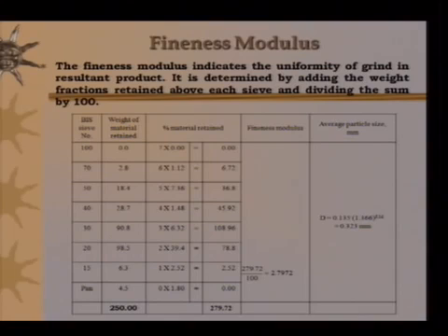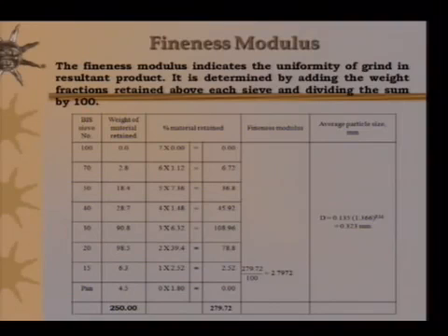The reason being that anything which you pound and reduce to a very small and fine size, you would like to know the uniformity of size in that mass. It is very important for, for example, the functional properties of wheat flour. Functional properties are good if the size is uniform. So in order to know whether the size of the flour is uniform, it is very important to know the fineness modulus.